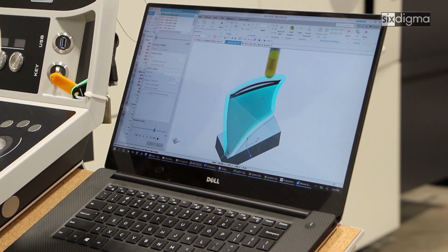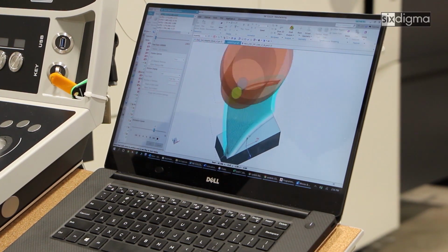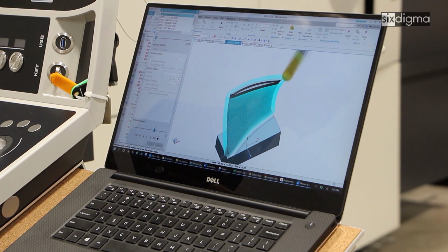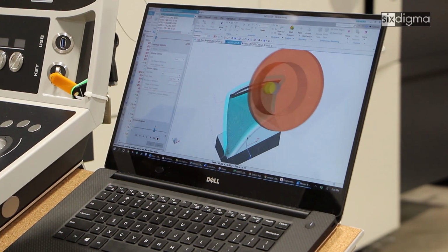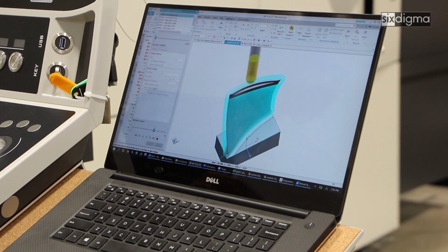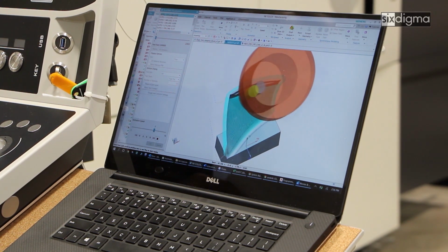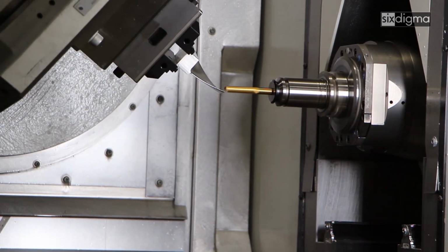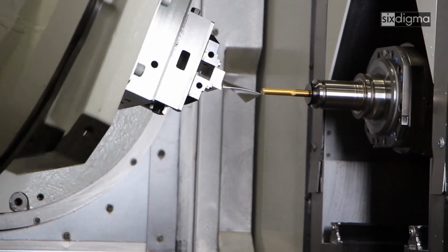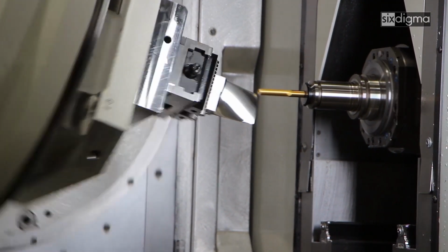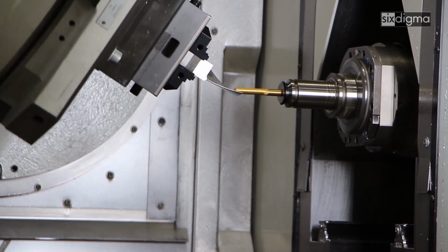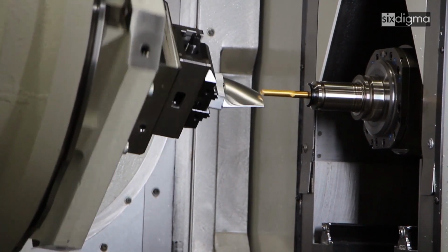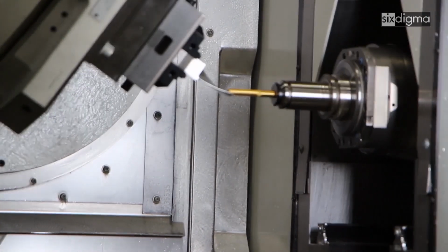Even if the rotary axes of the machine can respond quickly, the linear axes have to catch up and be in sync. Navigating around the tight leading and trailing edges always requires a high dynamic response from various machine tool axes. Siemens path smoothing options in Cycle 832 and Grob's customization of it for its machine kinematic and dynamic behavior produces excellent surface finish right out of the box.